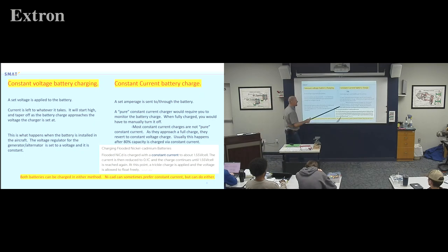That's why a lot of battery manufacturers are going to want this style. Let's say the battery healthily likes to accept a 10 amp charge, instead of having it take 40 amps for a couple minutes at the beginning, it says, no, we're going to limit it to 10 amps, and we're going to keep it at 10 amps for a certain time period or whatnot. I just pulled 10 because you could do them at whatever the battery's rated at.